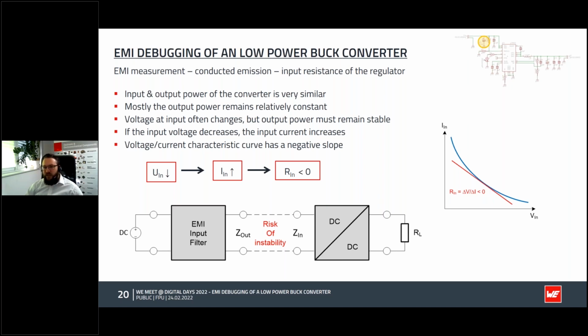These oscillations are caused by a so-called negative input resistance in combination with an LC circuit that is produced. Destabilization of the output regulation loop can occur when the frequency spectrum of the negative impedance at the input overlaps, especially with the bandwidth of the control loop.